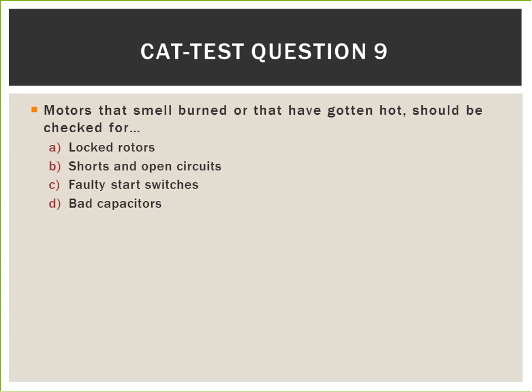CAT test question 9. Motors that smell burned or that have gotten hot should be checked for A, locked rotors, B, shorts and open circuits, C, faulty start switches, or D, bad capacitors. Answer B is the best answer here.